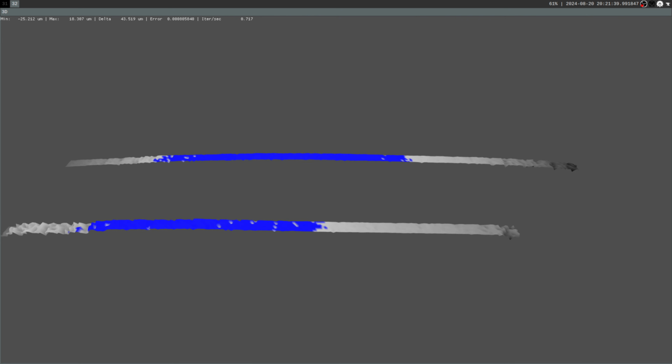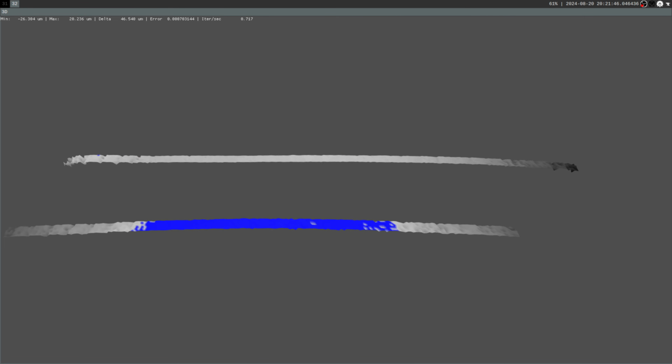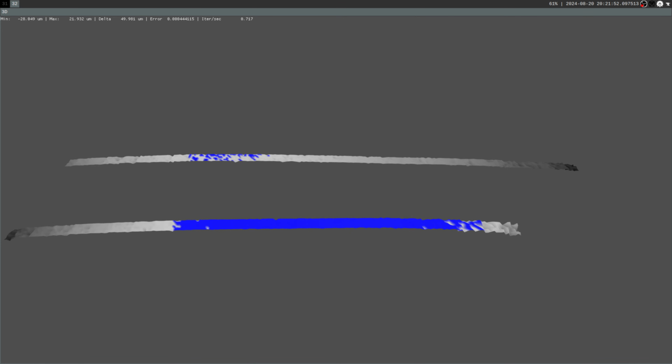So what I've been trying to do is model my lathe bed purely with my level. And my level allows me to theoretically measure things like twist and all sorts of differences between the beds that I can't do with a traditional, very simple straight edge.